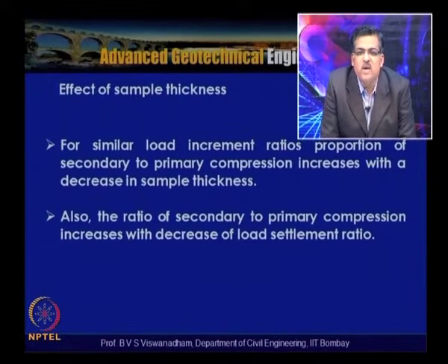So, for similar load increment ratios, the proportion of secondary to primary compression increases with a decrease in the sample thickness. Also, the ratio of secondary to primary compression increases with a decrease in the load settlement ratio.